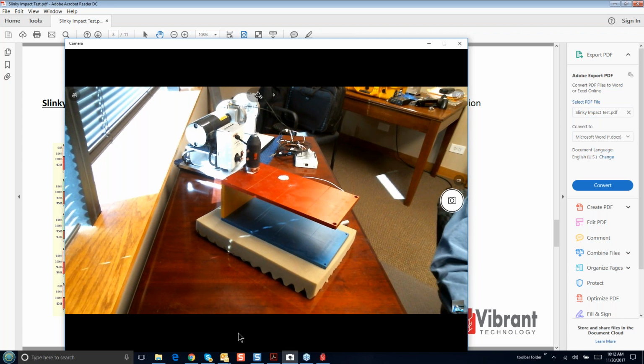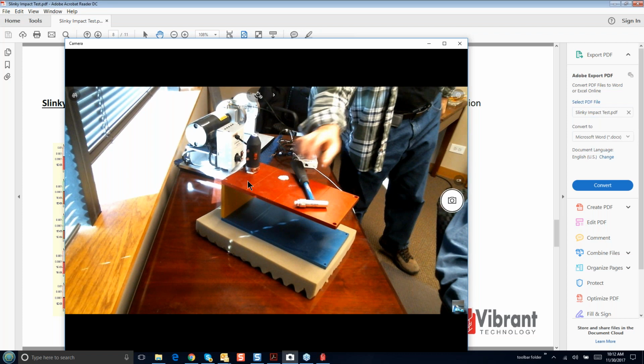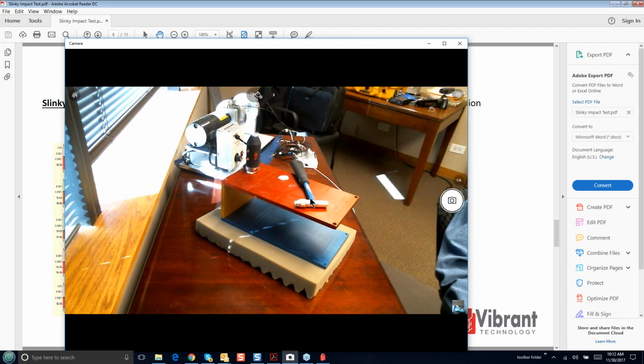So what you're looking at here is the GTI wireless accelerometer, and it's simply attached with some sticky putty to the top of this Jim Beam, and then the hammer has a wire coming out of it, but the wire is going into the side of this wireless accelerometer and transmitter device. So two channels of data are being simultaneously acquired in this device, transmitted through the air to the two sound channels in my computer, and then MEscope is picking up that data and post-processing it.